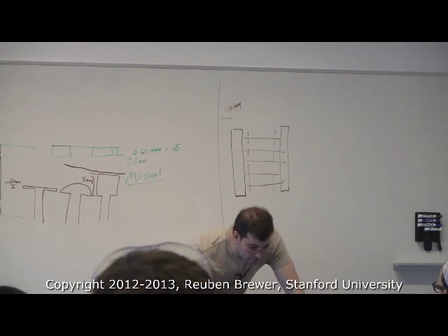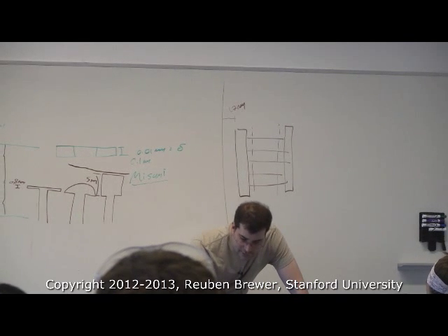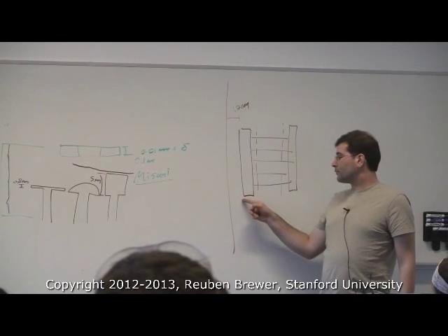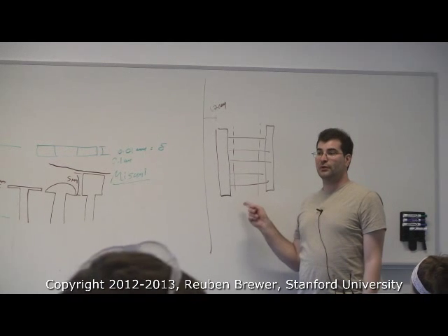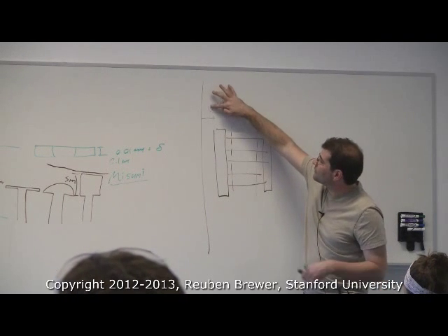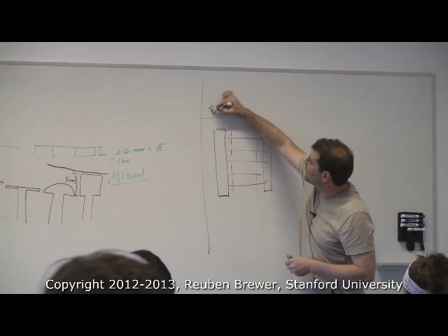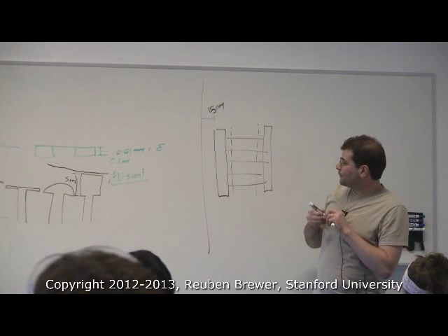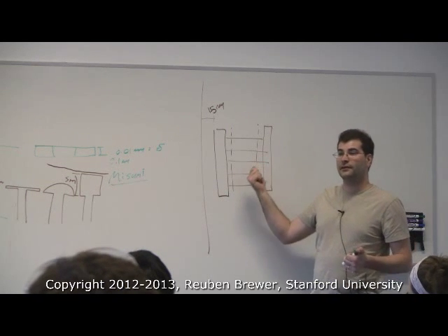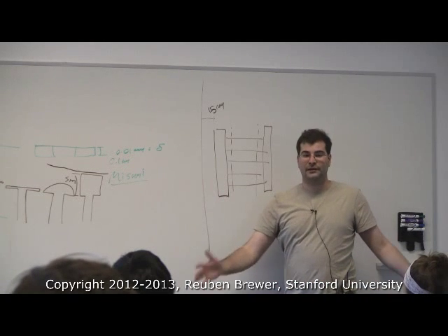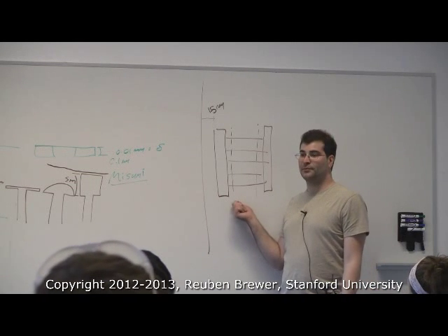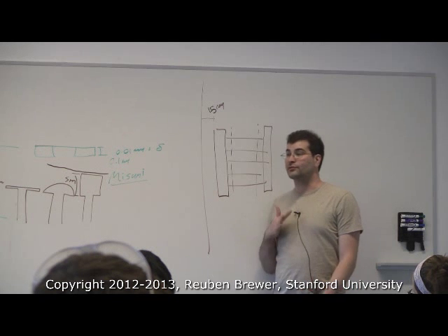So I'm going to show you a quick example. Actually, no, I'm not. Yeah, this is the example. So we don't need dowel pins or shims to keep this at this distance once it's bolted down, right? We only need 3 shims in here. I think I got lazy and said you could do 1.5. It was better than 0 or 10. If we use 3 shims here, we put the shims here, smush this against, tighten the set screw, and we're done. And this is something I want to be very clear on. Most of the time that you're using shims and dowels, it's not permanent. It's just to get to the proper installation height or distance or separation, and then you remove them to save weight.